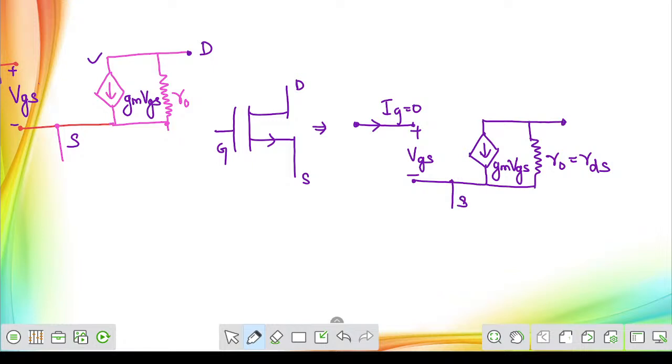All put together, totally we have three terminals, sir. So the terminals are, we can rename them as gate terminal, source terminal, and of course this is going to be the drain terminal. That's it. Understood, sir? This is how we are redrawing the AC symbol of MOSFET. As I told, this is for N channel MOSFET, so we are doing VGS and everything I have written here. If we are doing the same thing for P channel MOSFET, all you have to do is only one thing. In place of VGS, just keep VSG. That's it.